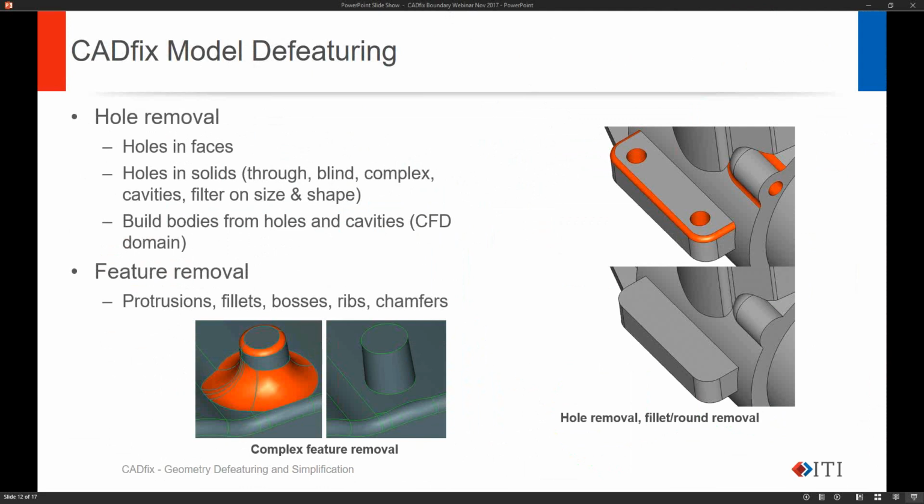Then we've got a feature removal tool. So if we were to manually select things like protrusions, fillets, bosses, we can then tell CADFix just to remove those features direct from the model.